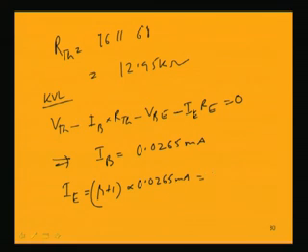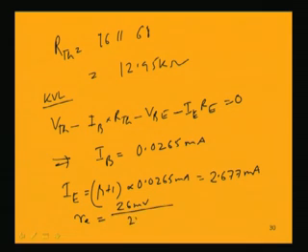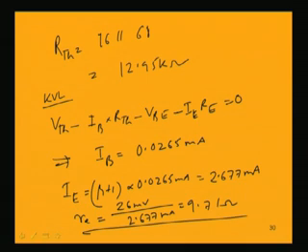So we get the value 2.677 milliampere, and so we can find out the RE value, that is 26 millivolt by 2.677 milliampere, and that gives us 9.71 ohm. Once we know RE, we can plug in this RE wherever required in our analysis of finding these parameters.